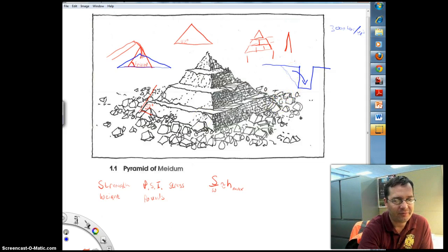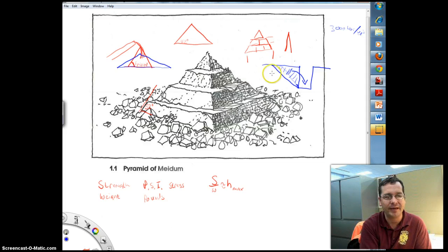Now, in attempts to prevent that, OSHA does have some rules about operating in trenches, and one of the rules is if you're going to go into this trench, one of your options is simply to cut this soil back with excavating equipment before you enter, so that you would excavate out all of this soil here. And if you think about what you're doing, you're basically cutting the banks back below their friction angle so that the soil is safe.